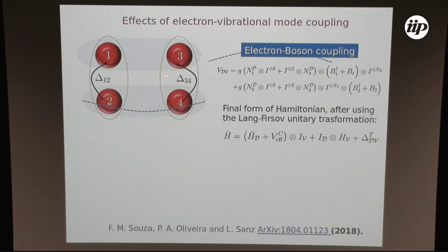In a similar way, dots 3 and 4 can be coupled by hopping, okay? The point is that the pi orbital in the carbon nanotube is perpendicular to its surface, so they can overlap with a parallel carbon nanotube, and you can have this nice hopping between them, right?